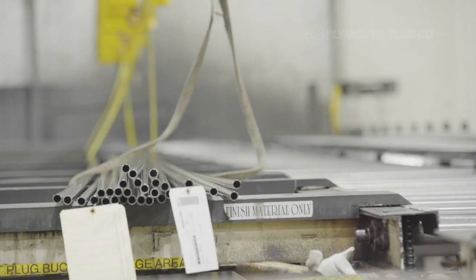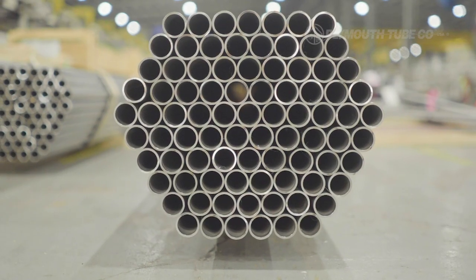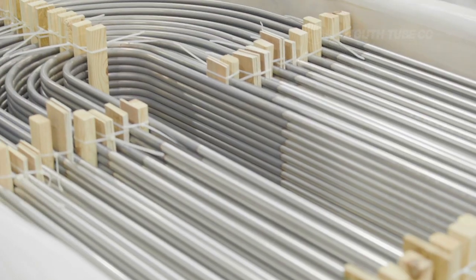In the metal tubing industry, there are a number of alloys and manufacturing processes that can be used to create products for various applications. Many of these products are manufactured to specified criteria or to requirements based upon customers' design parameters, but also to take into consideration the ASTM standards as they apply to their application. ASTM specifications define the chemical and mechanical properties, tolerances, testing, certification, packaging, and set forth minimum quality requirements.